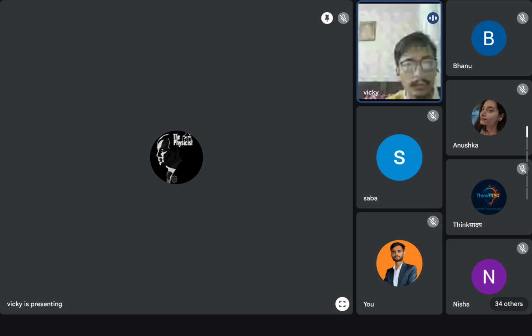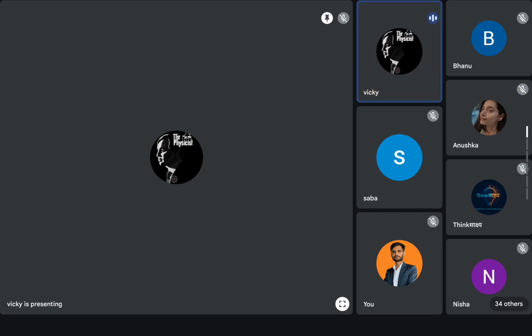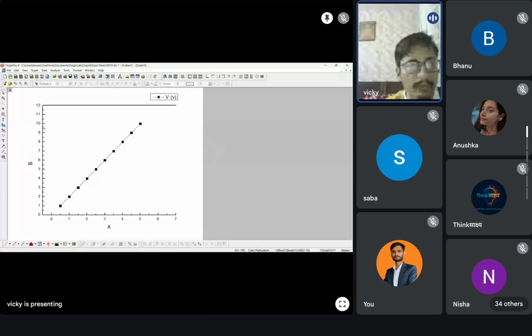Similarly, suppose you want to draw a line parallel to the y-axis on the very right-hand side, in order to complete your rectangle. So you again click on the axis, go to the grid line section, select the opposite option, and apply it. Now you can see how the graph is taking form. It's now very much better than earlier, right?